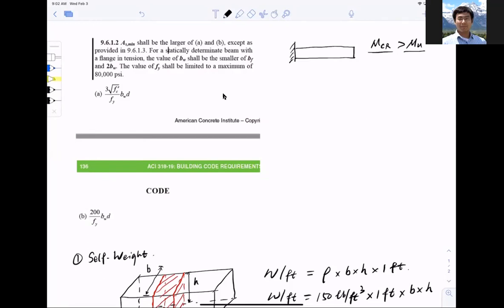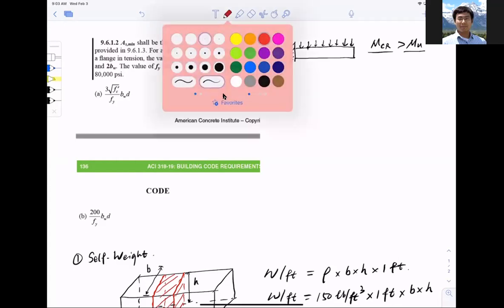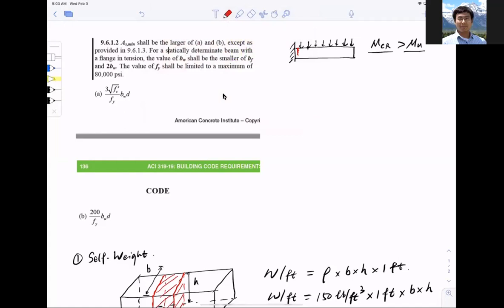So we went ahead with that design back then, but eventually the beam cracked. Knowing that it is a cantilever beam that only suffers self weight, the whole beam cracked right here on the end on the top. That's the major tensile crack. This accidental failure was a big note to the designers, because back then people thought, as long as my design is adequate, why would an accident like this happen? But there is statistical variation in terms of material properties, aging, and all that to do with concrete structures. So people decided based on this instance that we need to provide a minimum reinforcement.